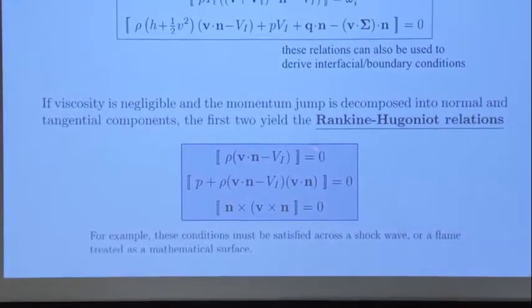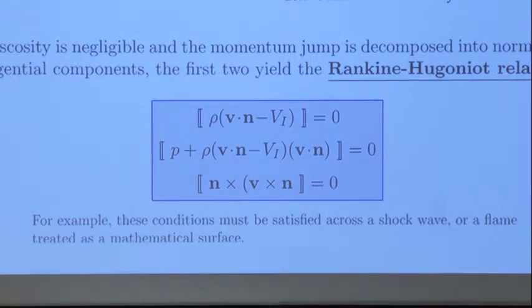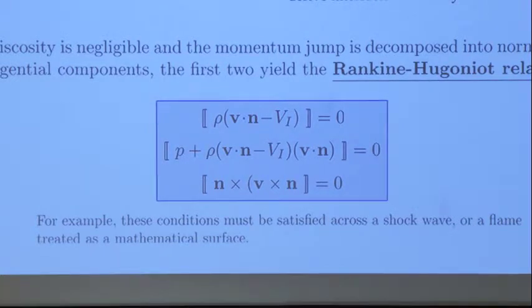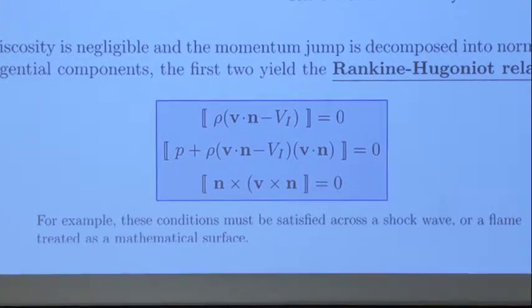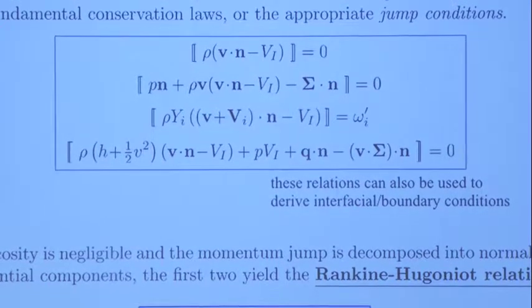Of course, I have eliminated here the sigma, the contribution of the viscous effect. There are many fluid dynamic problems, for example, film. In film theory, you have a film, and the interfacial condition is related to the fact that there are shear forces on one side but not on the other, and the boundary condition that you develop on the interface is essentially obtained from this expression when you satisfy it on both sides of the interface.